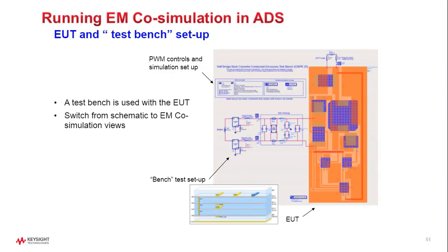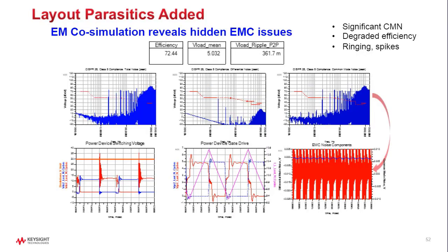All right, so the test bench I showed you earlier in the demo was a version of what I'm showing you here on this slide 55. It was an EM-based extraction from the test bench. It incorporated the substrate stack up and all of the artwork, and that's the point of this slide. The layout can come in as an import from ODB++. So that'll include the substrate stack up, material properties, etc.